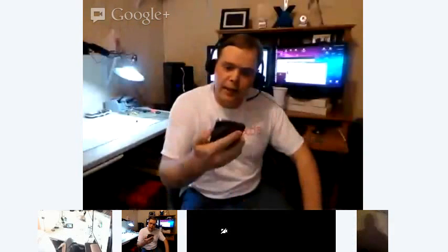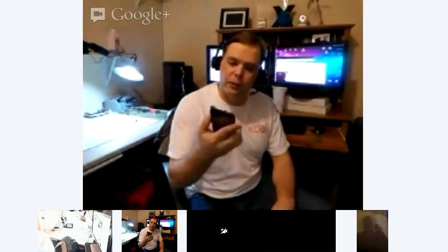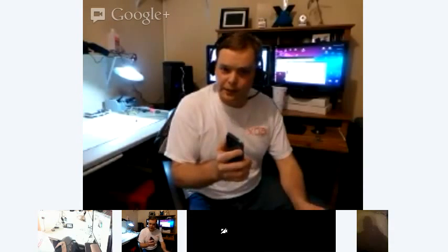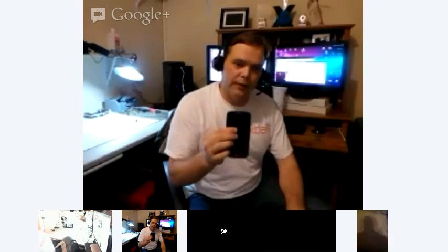Samsung Galaxy S3, and this is being broadcast live on my YouTube channel as well as on Google+. We're going to locate the UART port on the Qualcomm, I think it's ttyHSL0. So we're going to be trying to find the hardware output for that Linux device. And that's going to require a little bit of teardown.